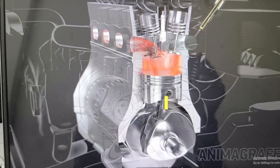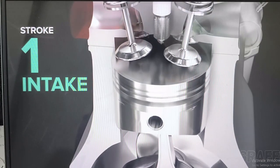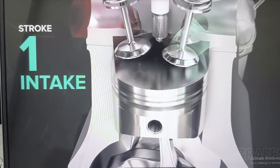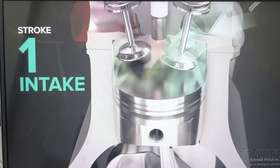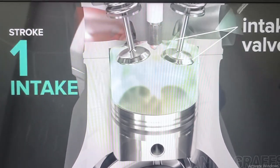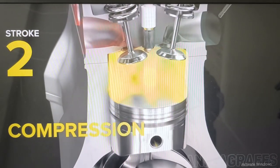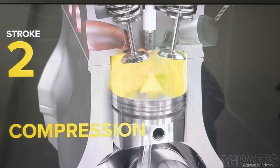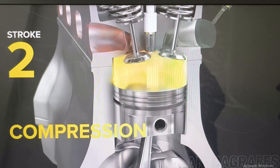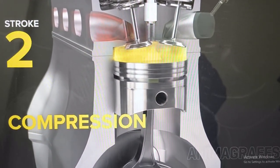Car engines use a 4-stroke cycle, and it goes like this. First, intake. The piston descends, sucking an air-fuel mixture into the cylinder through the intake port, with both intake valves open. Next, compression. With all valves closed, the piston comes back up, compressing the fuel and air mixture for more powerful combustion.